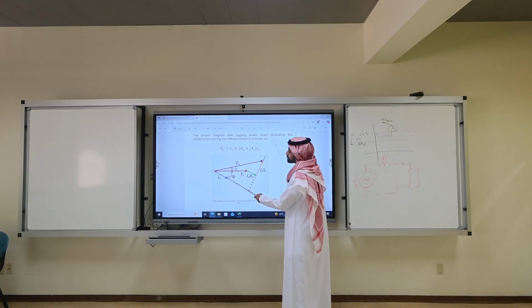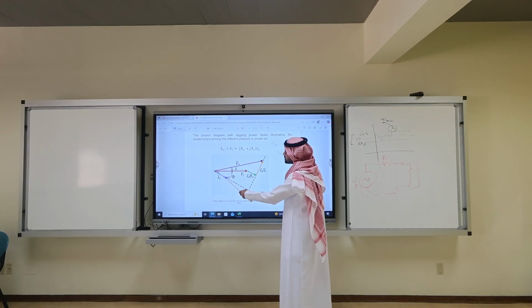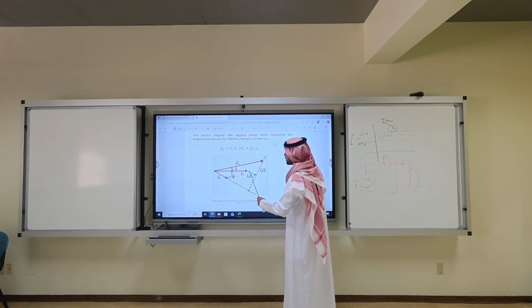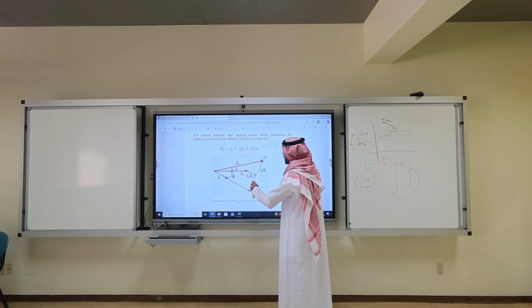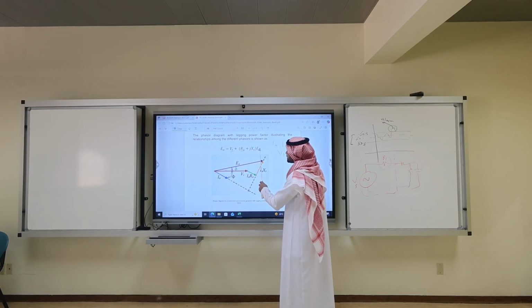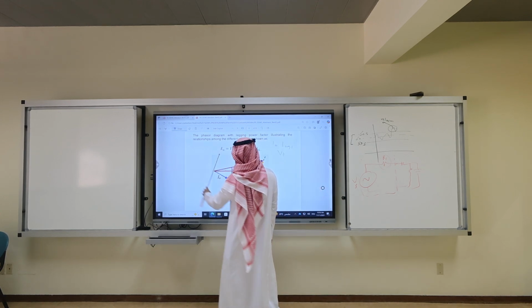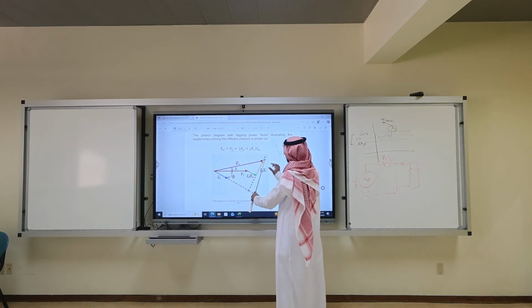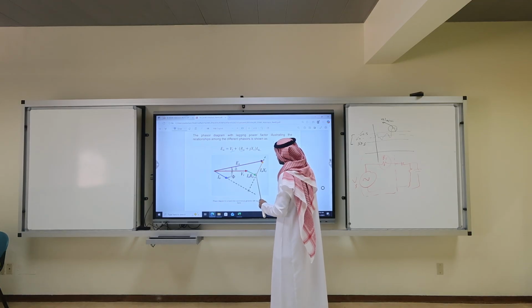So that's my Ia. Multiply Ia by Ra, it's nothing but a scale up or down. So the green curve is the blue curve times the scale. We connect the head of the red curve with the tip of the green curve. So I have Vt plus Ra Ia plus jXS Ia. J is 90 degrees, so I should have Ia rotated by 90 degrees. So it's the yellow curve plus some scale, which is XS. So I added vectors.